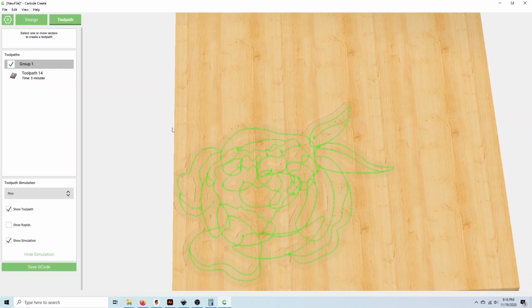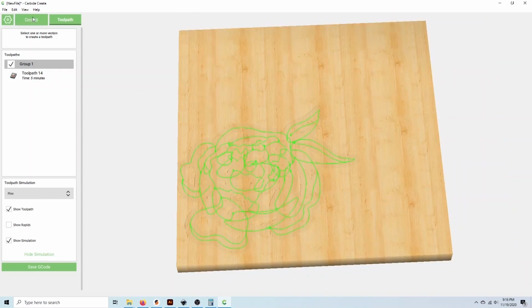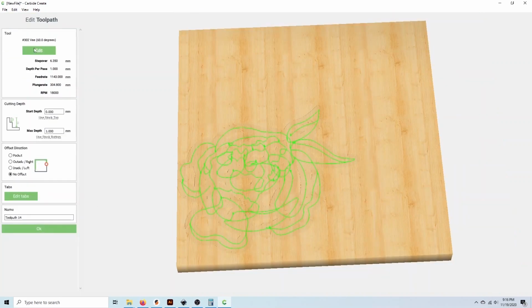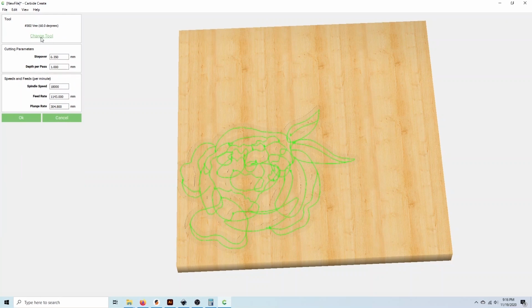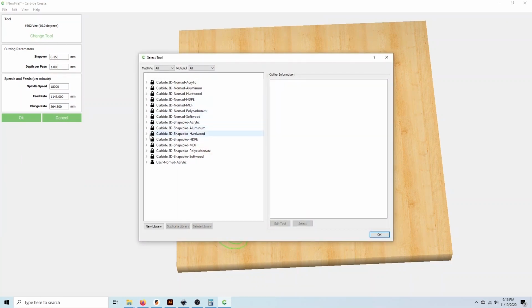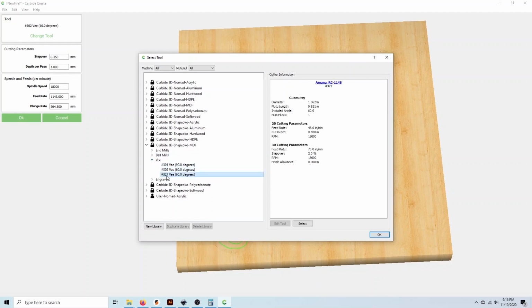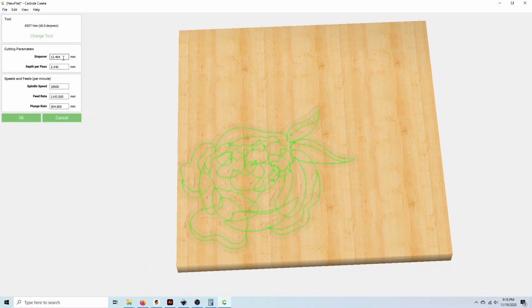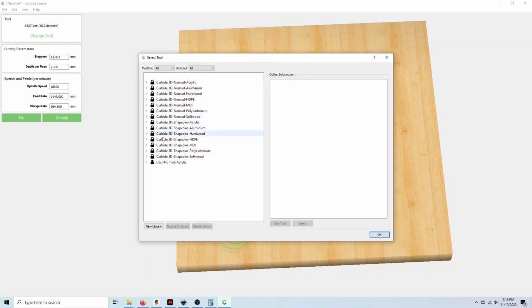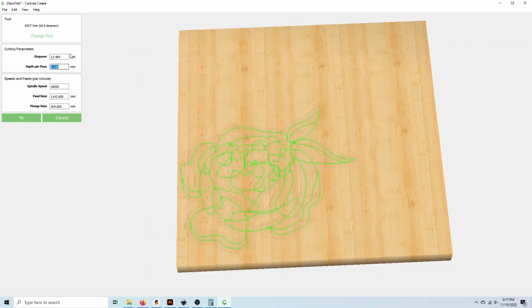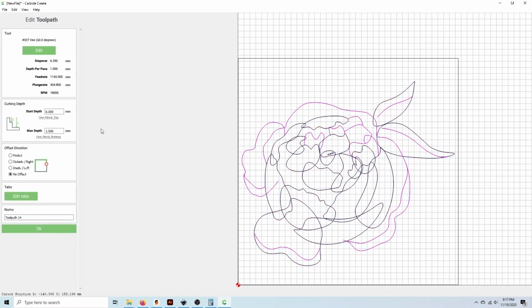So I finally decided to go back to using the contour toolpath, but this time just select the bit to be the 60-degree V-bit. I just chose one that was similar to what I had on hand, and I also used the default settings for the Shapeoko for MDF. I thought the LongMill and Shapeoko were comparable machines in terms of capability, so I thought the settings would work for the LongMill as well.